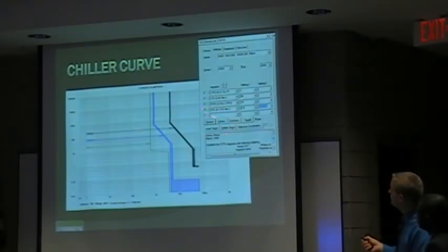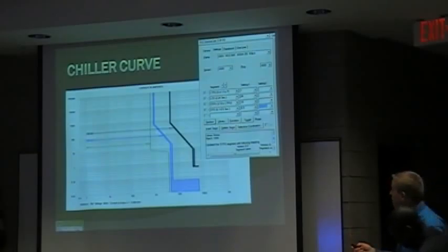And the short time delay, we set that at 0.5 seconds, so if there was a high amount of current happening, it would sense that and trip within 0.5 seconds. Yeah, 0.5 seconds.